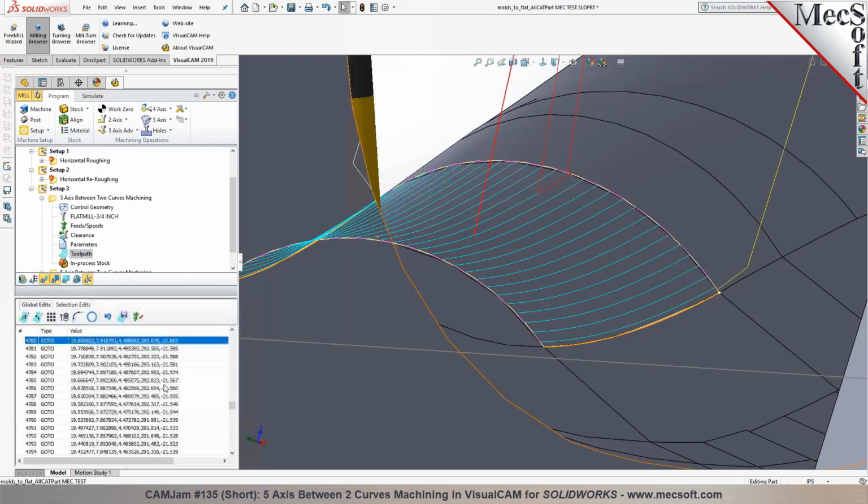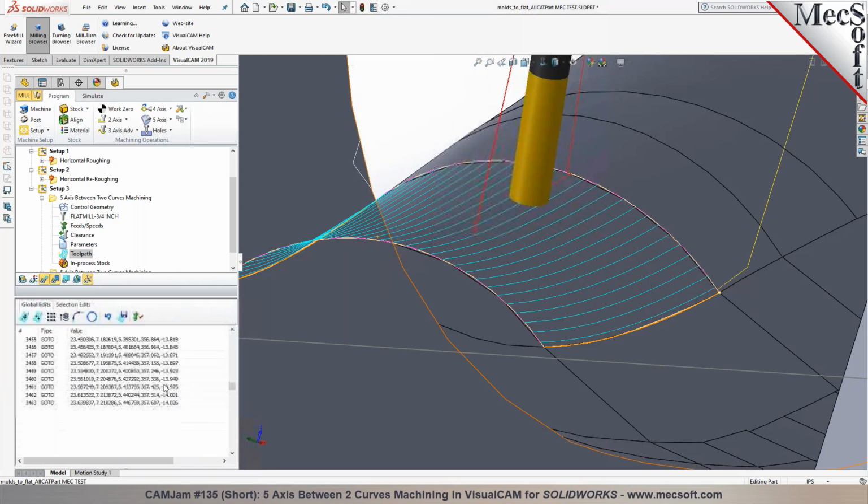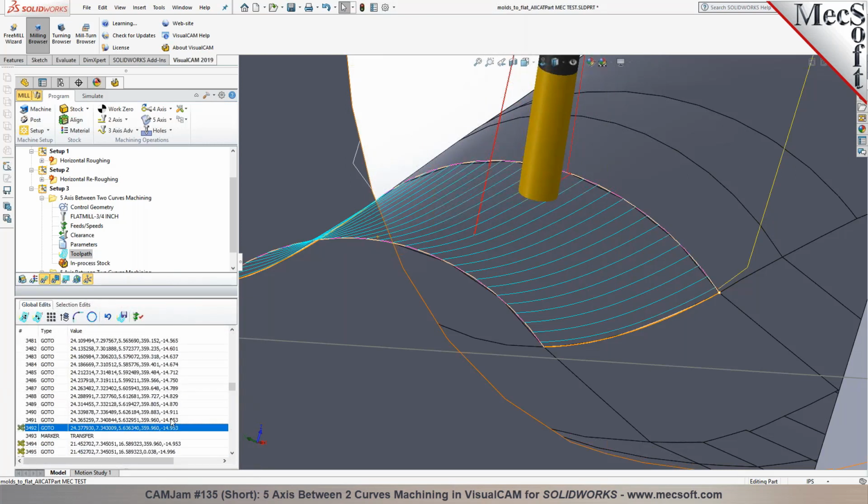Okay. Does the software know, like in our machine, let me see how I could explain this. In positive X, the C-axis 0 is to the left of the Z-axis in the X positive. So in other words, from the top view, as it begins to rotate counterclockwise, positive direction in the C-axis, the 0 is in line with the X positive. So does the software already know that, or is that something I have to tell it?